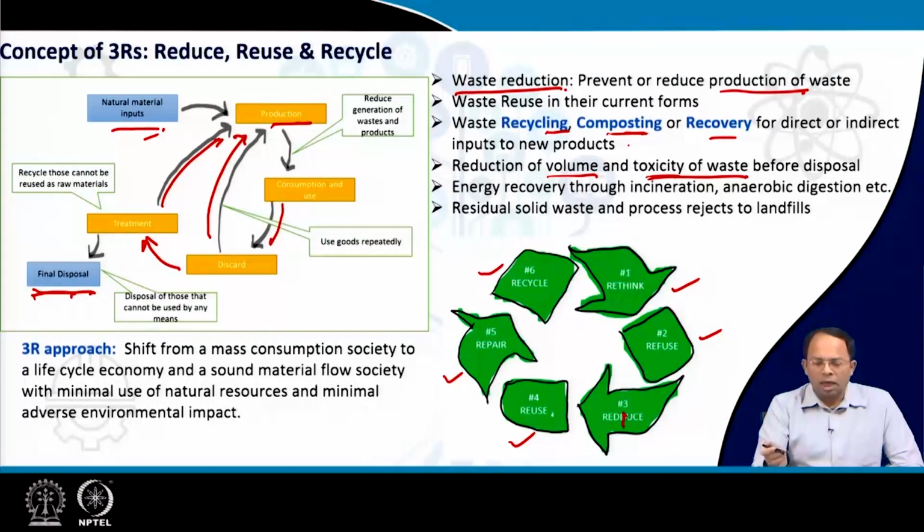some amount of energy. We have already learned this earlier, that if the waste has a calorific value higher than a particular threshold, which is 1500 kilocalories, in that case we can actually burn that product to produce energy, right? So either by incineration, or by pyrolysis, or this kind of combustible technologies, or in other technologies like biomethanation, which are chemical biological processes, we can also generate some amount of energy.